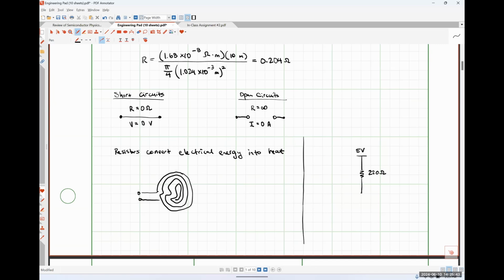And then you had an LED. The purpose of that resistor was just to limit the amount of current flowing through the LED, because the resistance of an LED is actually rather small. And because it's made of sensitive semiconductor materials, it burns out very, very easily if you apply too large of a voltage drop across it.